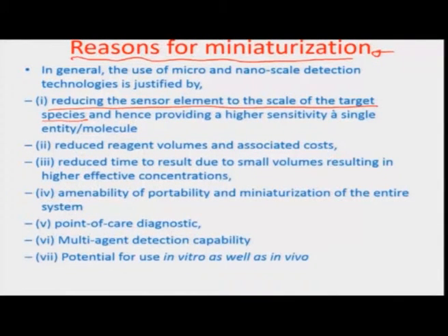So, we must understand something, that when we are detecting a small cell, let us say for example, a biological cell which is about 20 microns, or a bacterial cell which is about less than 10 microns, and we are doing it with a surface which is probably a few hundred millimeters, then obviously there are issues related to how this surface would interact with such cell, and there are going to be its own inertial delays, because the surface is extensive in terms of the sizes as compared to the target of interest, as opposed to if we were to develop a surface which would be exactly similar to the dimension of the particular species, the inertial response may not be that big of an issue in the signal that the sensor provides you.